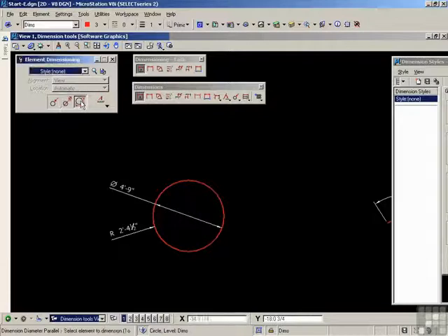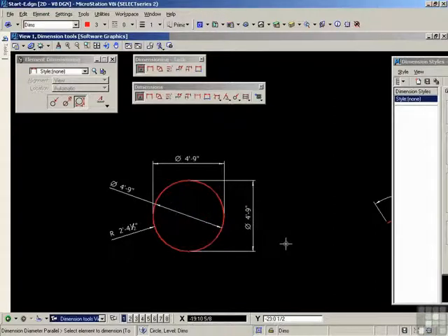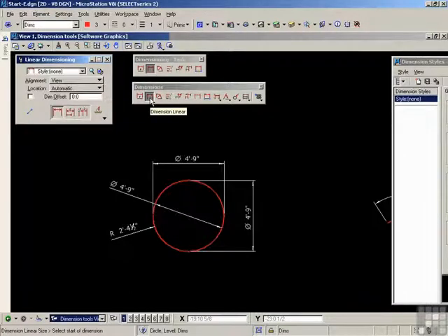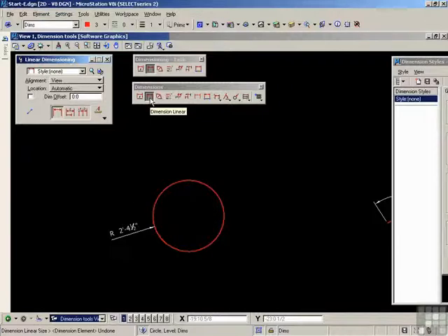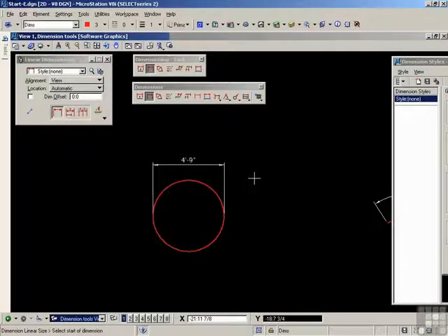Or we can dimension in typical horizontal or vertical style. Simply depends where you select the circle. And they're quite useful options, and sometimes quicker than actually starting the radial dimension tool. You can also, of course, use the dimension linear tool too. And I'm going to undo those previous dimensions so we can have a little space. We'll start with this one. Now, of course, you're simply selecting data points. Data point, and extension. Now, the only drawback here is that the extension lines appear to contact the circle, but we can fix that if necessary.